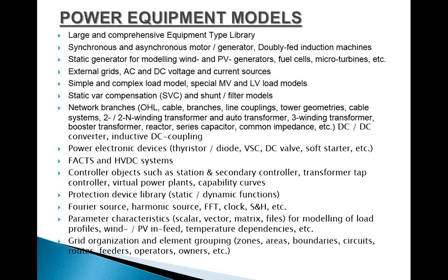These days, complex studies for integration of wind generation into distribution and transmission networks have become very important. And PowerFactory comes with the standard in wind generation modeling, combining extensive modeling capabilities with advanced solution algorithms, thereby providing analysts with the tools to undertake the full range of studies required for grid connections and grid impact analysis. Some of the study cases we can generate on wind generators are steady state load flow calculations considering voltage dependent reactive power capabilities, and also providing limits to wind farm controllers with set point characteristics.